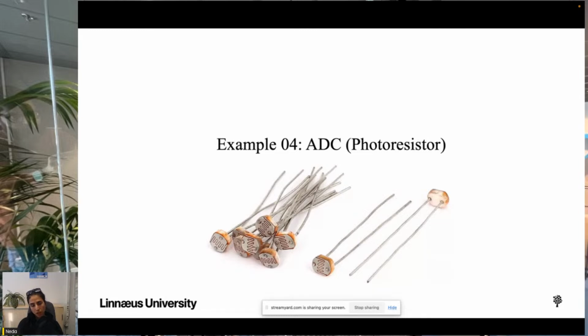As this sensor works as a simple resistor, you will not get absolute light values, for example, lumens. Compared to a reference voltage level, that is the 3.3 volts provided by Raspberry Pi Pico W, you will read a value less than or equal to Vref, reduced proportionally to the light exposed to the photoresistor.